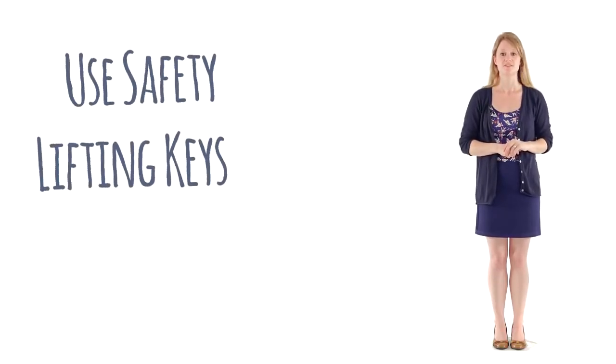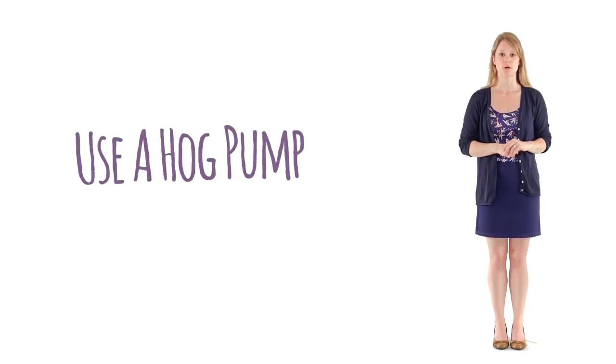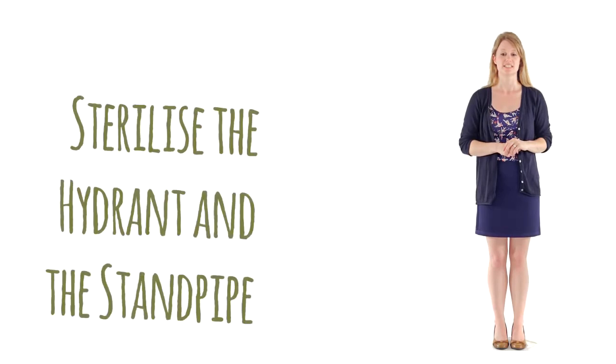So, let's recap what we've covered. When working on a hydrant, remember to use safety lifting keys to remove the cover. Never put your hands in the gully. Stay safe and use the correct proprietary tools to clean the hydrant. Use a hog pump to remove any water. Sterilise the hydrant and the standpipe before use. Open the hydrant slightly to flush out any contaminants.